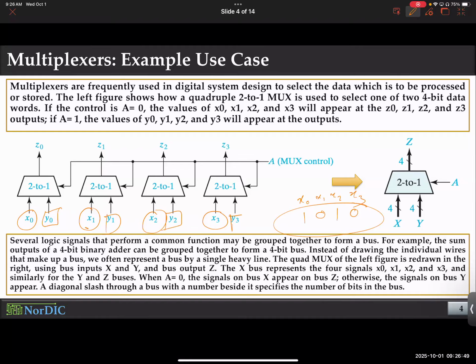And you want to select one of these numbers, one of them, not both simultaneously, all right? So you have 1010 or 1111. You are choosing between either of them. So this is one way to do so. Since you're choosing between two numbers, it's either A or B, say. You can connect every bit of one of the numbers as an input to a 2-input mux, and the corresponding bits of the second number as input to the same mux, as you see.